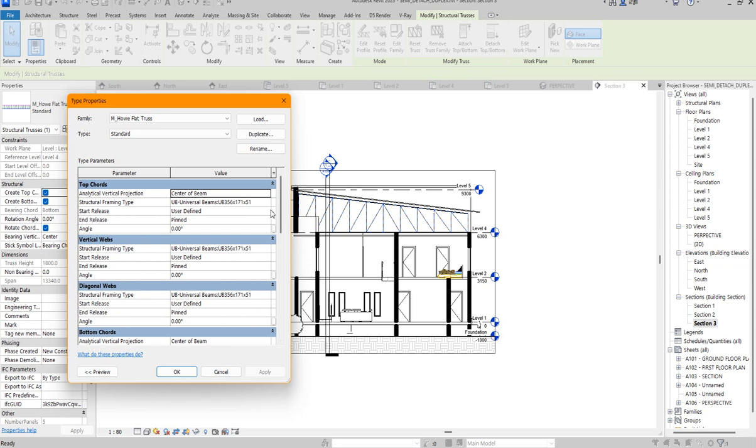Single element, you want to change it to concrete, depends on what you want to do. But one thing you are doing, by the time you are doing the bottom one, let it just be a center beam. So when you click that, you can decide to change it, depends on your choice, but I always prefer to use that center beam. So now click on this one. I want to change the universal beam for this. So when I click here, let me say apply.